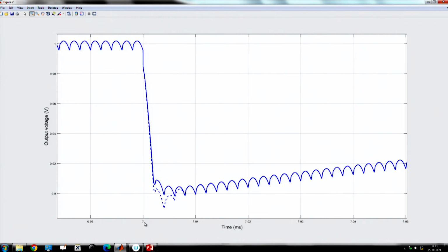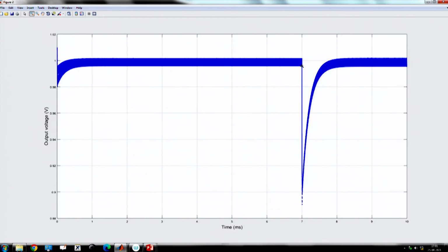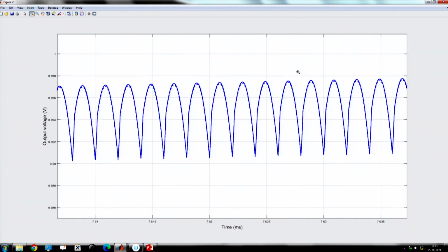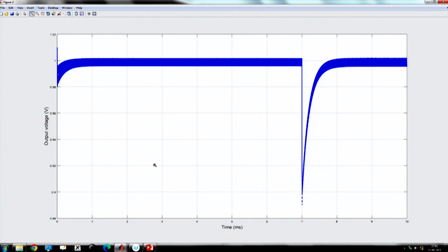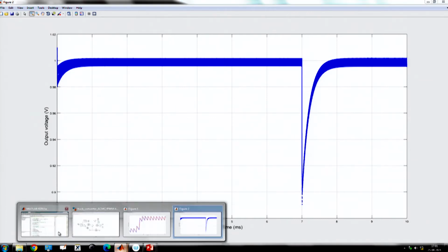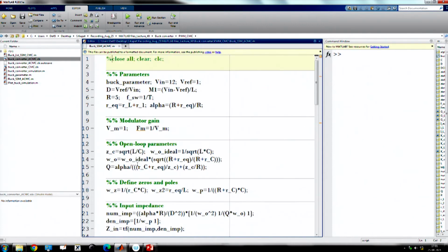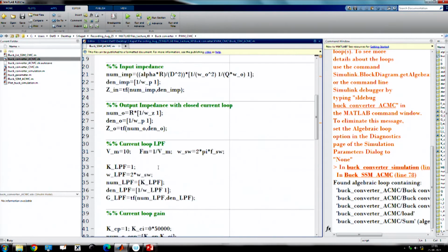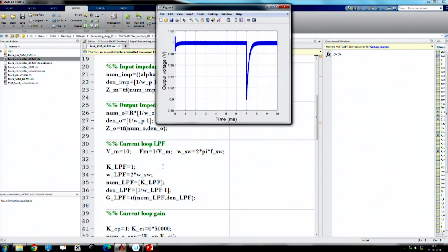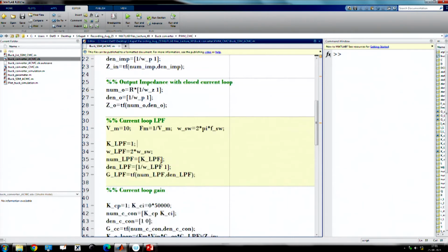That means you see the output voltage, okay. So, the speed of the response will be affected, but not very drastically. There is no drastic effect, because your voltage loop bandwidth is already slow, not very high. But now, if we take this example and we want to further reduce and make it 1/2. So, this is with 2 times the switching frequency.